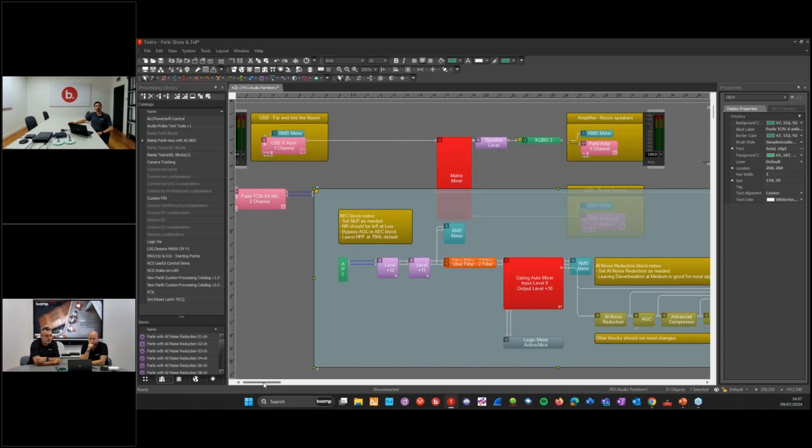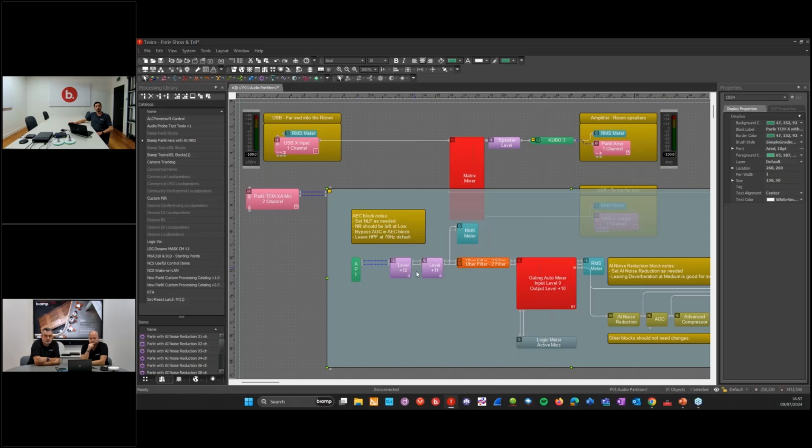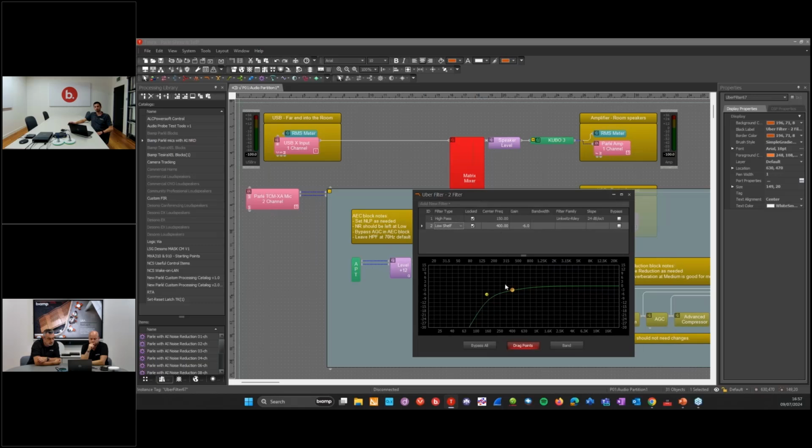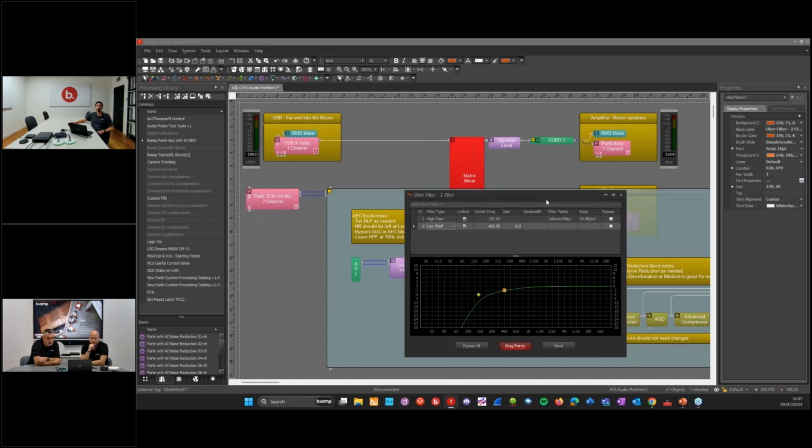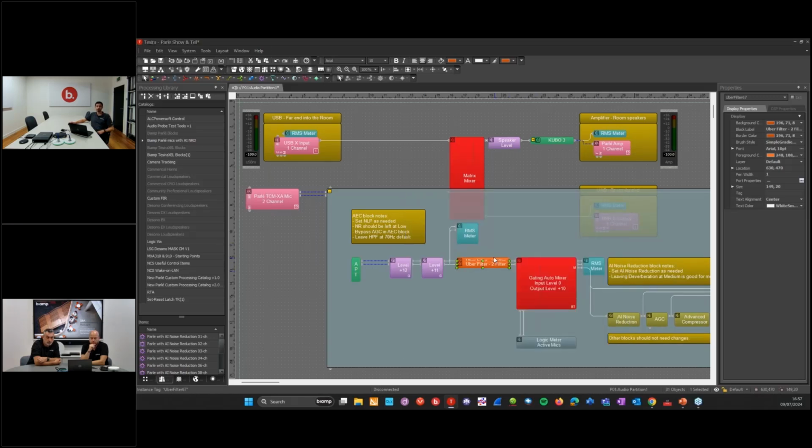Now you see we're actually adding slightly more gain at the front end. The filter blocks are set this way because we can use the AI to clean up the reverb very, very well. We're just going back to filtering off the very low frequencies to prevent that low frequency buildup. We let almost all of the mic pickup through, and you'll hear that the mics are very full, smooth, and natural, and have really, really good pickup. When you get those tight beams, it sounds really good.